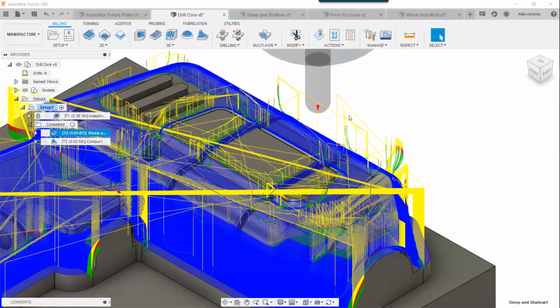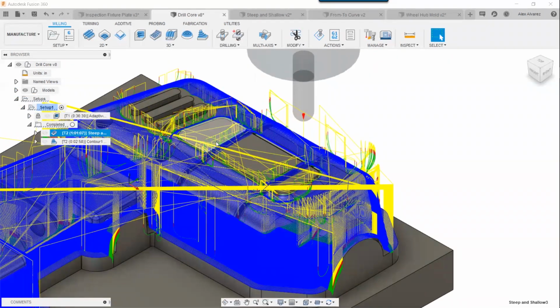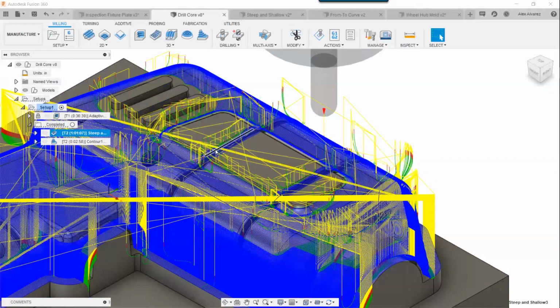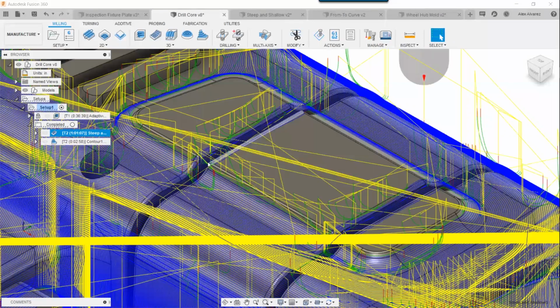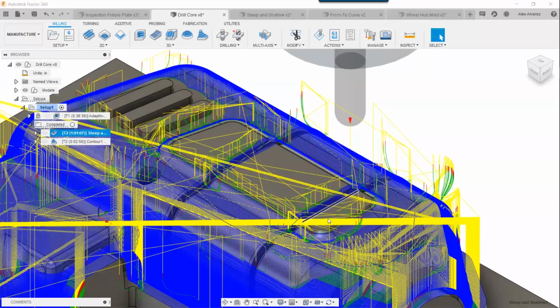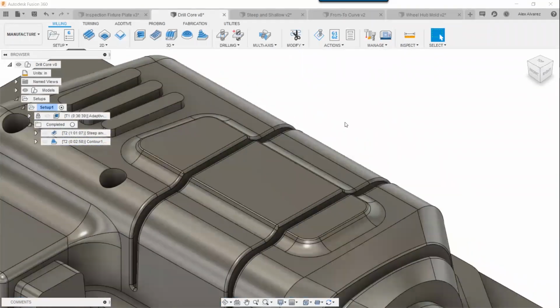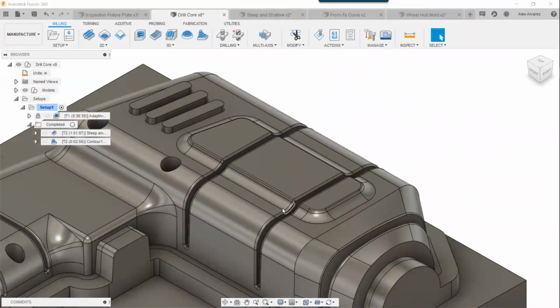Here's the toolpath here. Again, I can probably do a little bit better job. And personally, if I was working on this model, I would actually make a few modifications. One of those modifications would be getting rid of these little slots, either by doing some sort of surfacing strategies, using the surfacing tool in the design workspace, or just completely getting rid of them using the direct edit modeling capabilities inside of here, right? Because again, we don't want the toolpath to read any of these